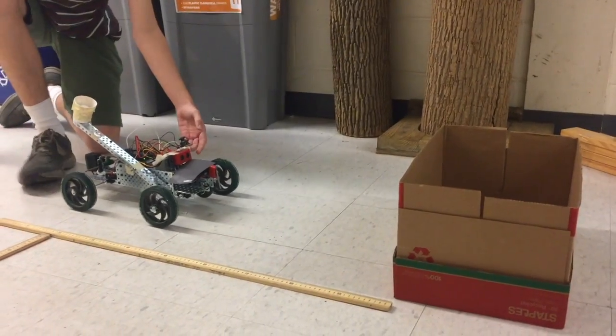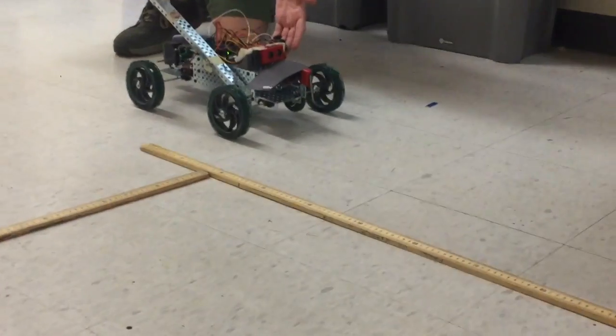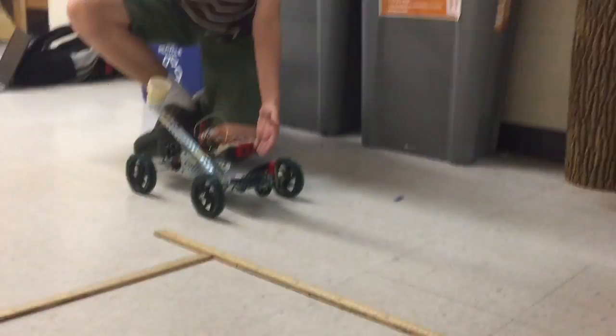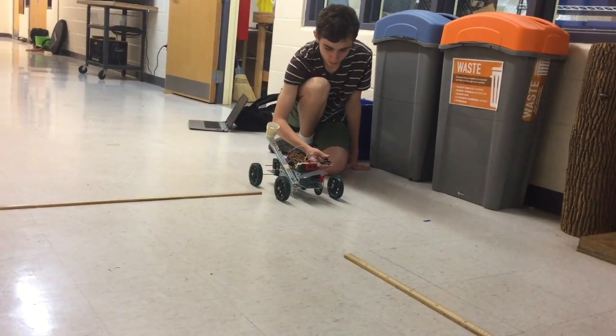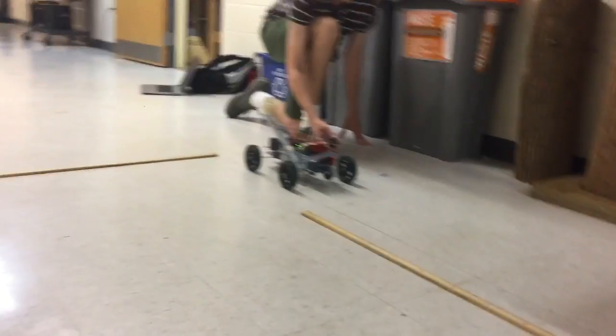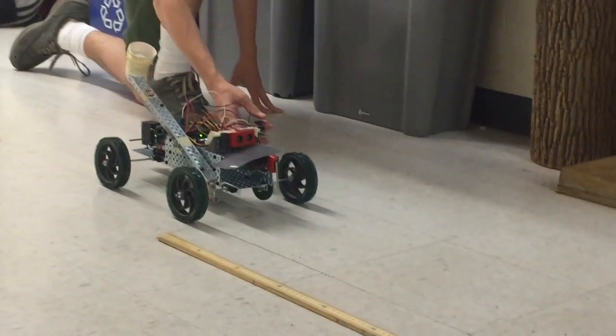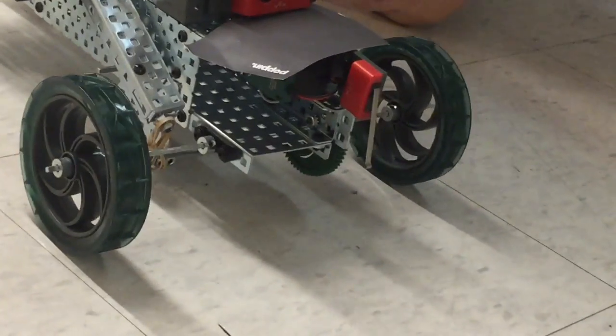And the last and probably most complicated function is the actual distance sensing itself. The distance sensor senses the distance, and when the joystick is not being pushed forwards or backwards in the y direction, when it's just idle, it moves backwards or forwards depending on its distance until the robot is 100 centimeters away from the object it's trying to shoot.